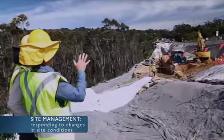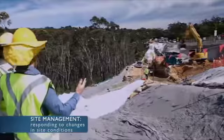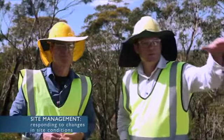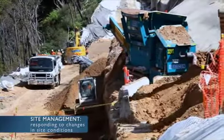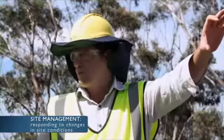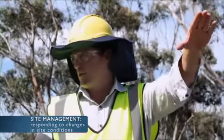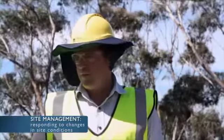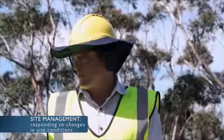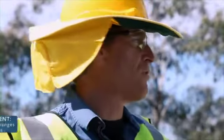This is a perfect example here because we've got a lot of major work and a lot of changes happening in this section of the road. What you can see here is we're constructing one carriageway, building a wall to construct that carriageway there. At some point, we're obviously going to have to shift the traffic from the existing highway onto that carriageway so we can then finish the project on the other side. Yeah. So we're going to have major changes to drainage through the course of the project. If our controls aren't in place to manage those changes, we're going to be in trouble. So proactive planning, Chris, and keeping on your toes with the changing site conditions will minimise erosion and the sediment.